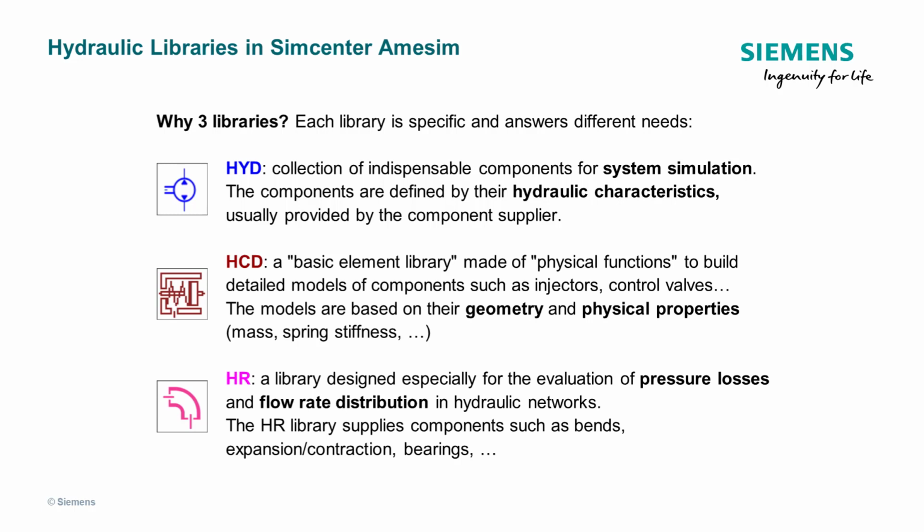Compared to the HYD library, the hydraulic component and design library is used to focus on component-level modeling tasks. For these HCD components, it is the geometry information and physical properties that govern the calculation, instead of characteristic curves or data table used in components from the HYD library.